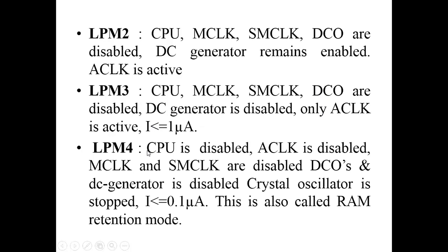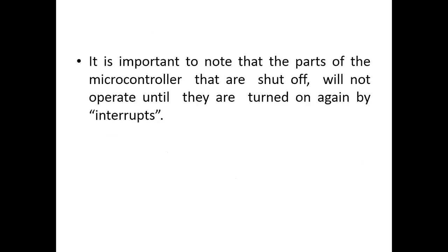Coming to the last power mode, all are disabled, even the ACLK. Because of this, the current consumption is reduced to 0.1 microamps. This is also called RAM retention mode, meaning only RAM retention is available. The remaining are all disabled.